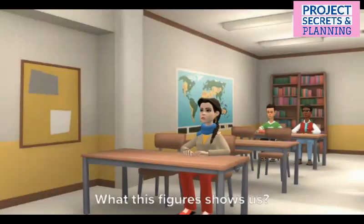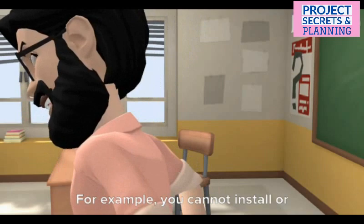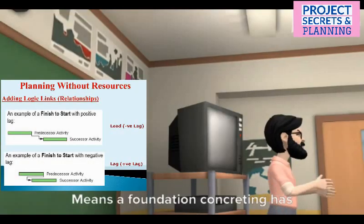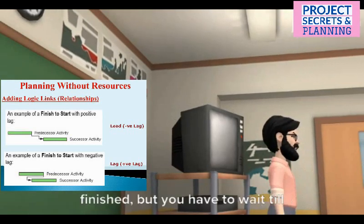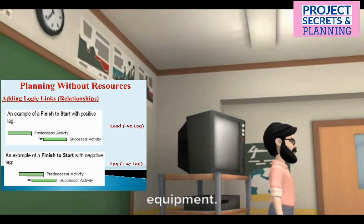What does this figure show us? Lags are those durations by which you delay or make your activity earlier against your logic. For example, you cannot install or place your equipment on a foundation before its curing. Meaning the foundation concreting has finished, but you have to wait till its curing time to install or place equipment.